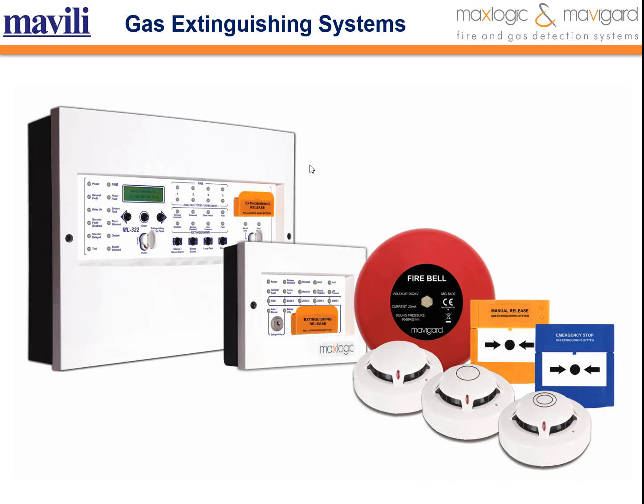The extinguishing panel consists of 4 zones. It can be adjusted which of these zones will have the ability to initiate extinguishing, as I told you from the previous slide. You can use the cross-zone working mechanism with all 4 zones. With the LCD screen and LED indicators on the front of the panel, the operation status of the panel can be monitored in detail. The power supply of the panel has an automatic battery charging and control circuit.